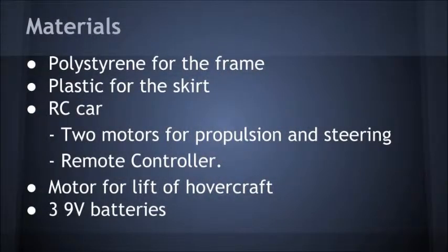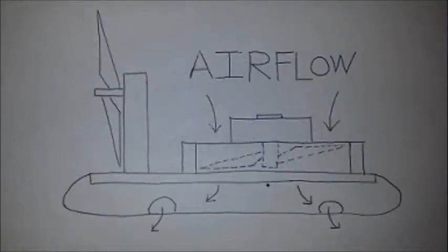Once lifted, the 2 propellers on the tail of the vehicle will provide thrust needed to push the craft forward. To steer, we apply the double propeller system. If the right propeller is turned off, while the left one stays active, the total force done will help turn the hovercraft to the right, while the opposite action will turn it to the left. All motors are powered by 9-volt batteries and connected to a control board for remote control.